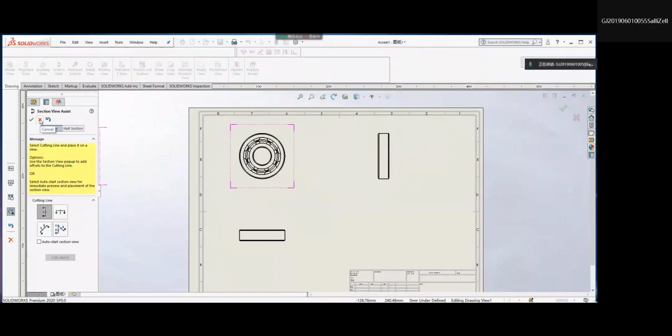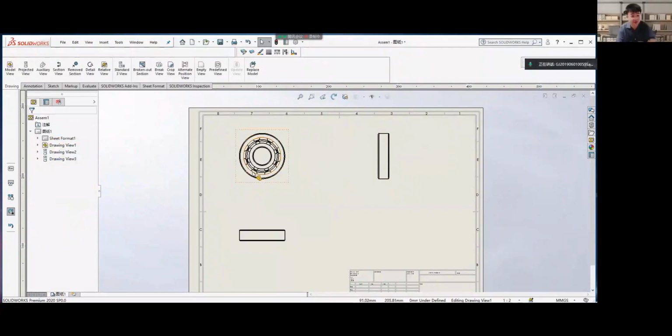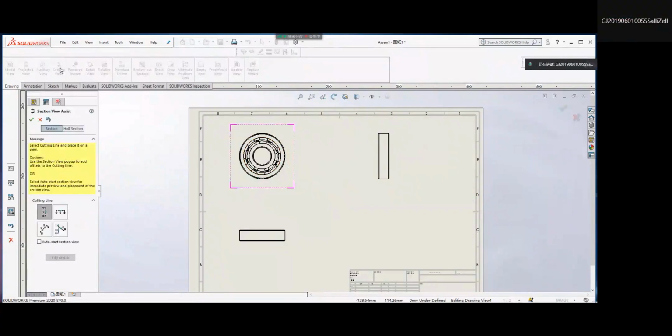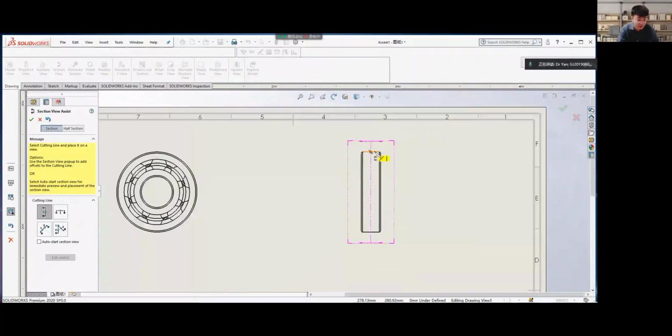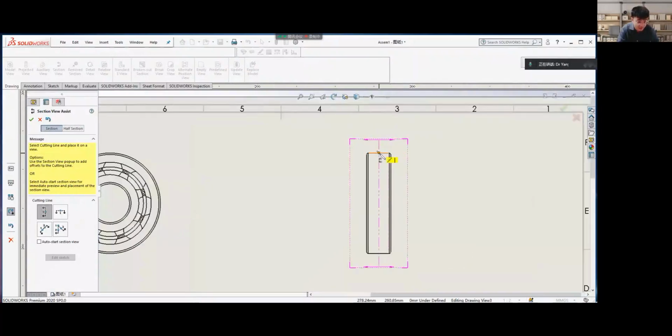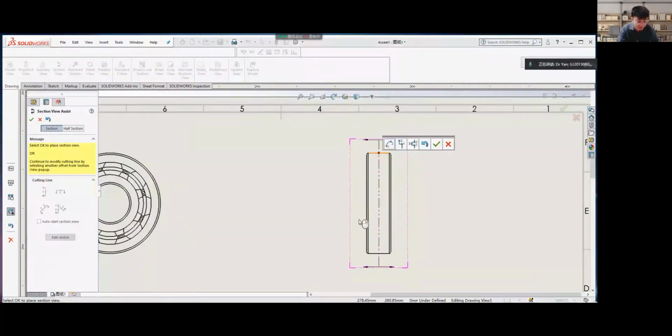It's a little faster. Okay, I have to do it slowly. From here, right? And you should see the section view in the drawing. Okay, let's click the section view. And this one here I choose is the vertical, right? Because I want to cut this thing in 2 parts in the vertical direction. Okay. Let's select the middle point. Okay.